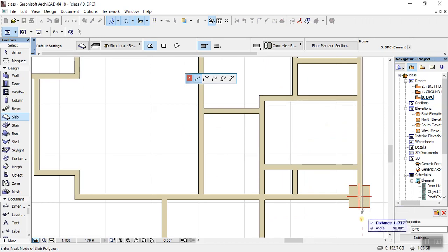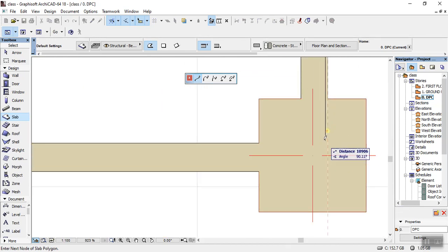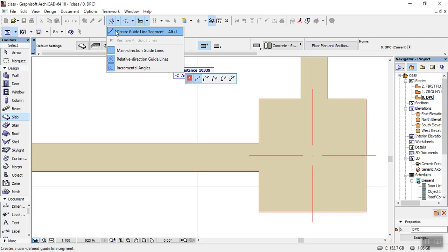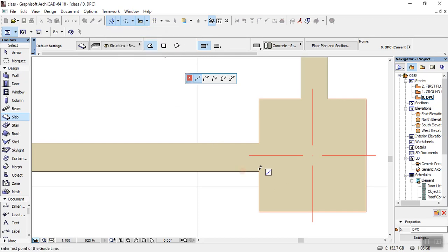Then at this spot right now, you know there is a column here, so you can't see this end point, except you just want to guess. But you really don't need to stress yourself. What you just need to do, while this command is still going on, you come down to the spot, you pick your guide tools, you click create guideline, you come down to the spot, you create a guideline, then you place